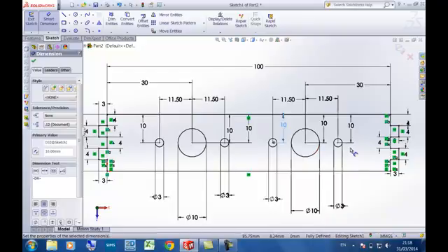One tip I can give you is when you use Smart Dimension, make sure the orange dot lights up, and then click on it, and then move your cursor over and make sure the line also lights up in orange color, and then you click, not drag, just move your cursor over and click again to input the correct dimension or number.